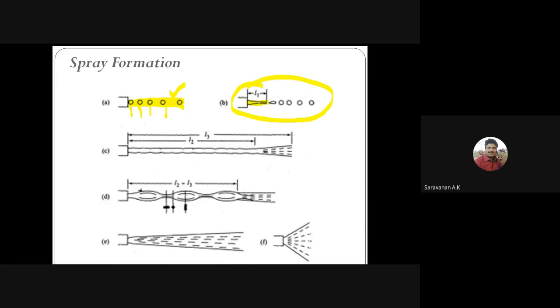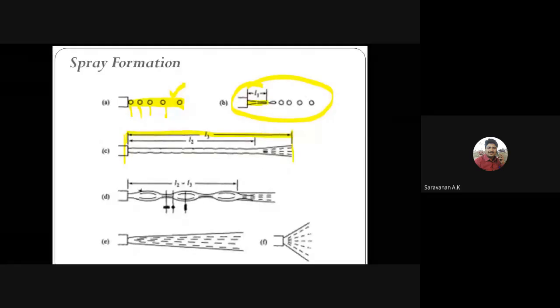So in the combustion chamber, we get a compression ratio of a minimum of 12 to 14, right? And the fuel breaks into the spray at this distance from the nozzle outlet. So from here to here, after that the stream will be developed like this.